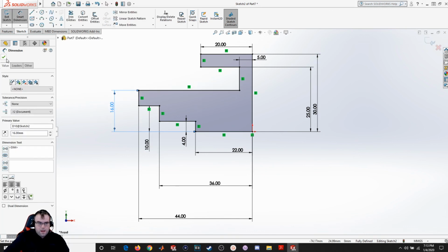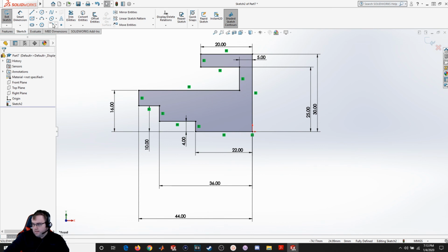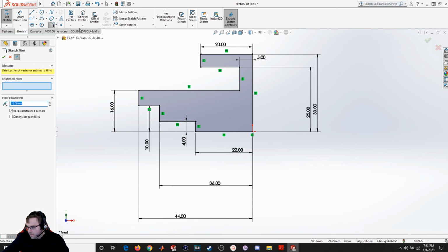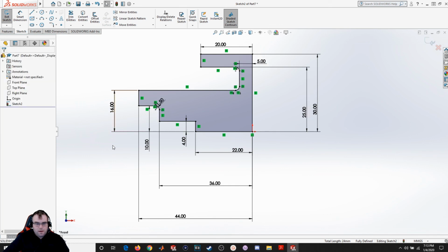Here we go. Now I just got to add in the fillets. Let's see, they're all 1.5. So I've got one here and here. Oops. This is too big to fillet, so I'm going to put 1.5 in now. And then I'm going to select this line. There we go. It'll let me do it. This line and this line. And this line and this line. And, yep, just those 3. Hit OK. And I've got my finished part.